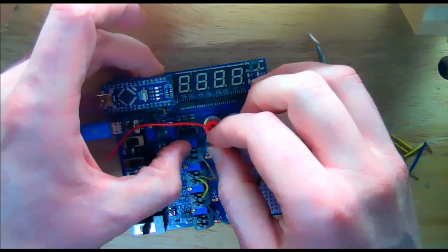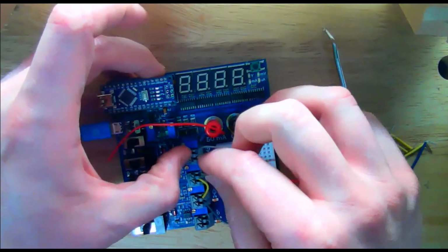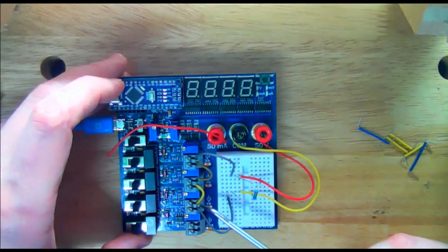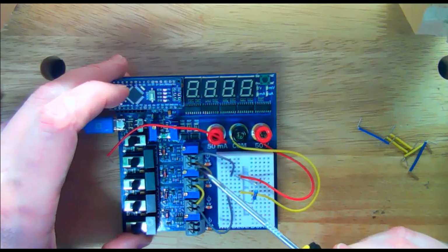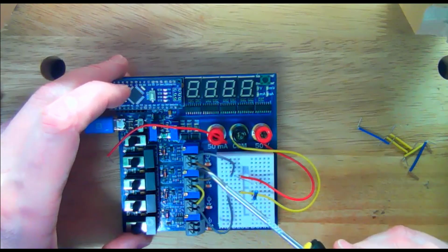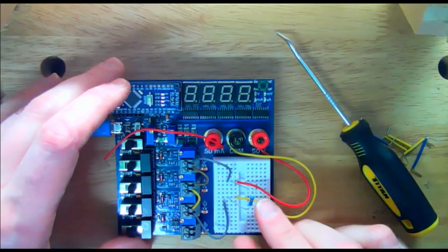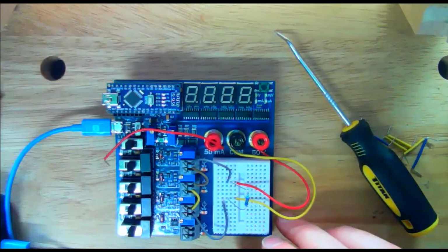I just want to really quickly just give an introduction to this board. So, okay, so now we have the positive of this bottom 7 connected to the negative of this 7, the positive of this 7 connected to the negative of the 3. So this should be 7 plus 7 plus 3. This should be 17 volts. Let's see if we're able to generate a 17-volt supply here.